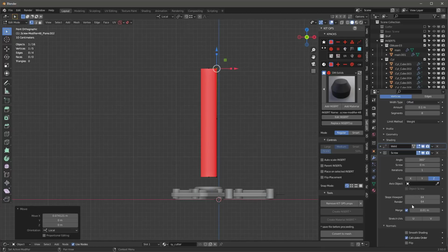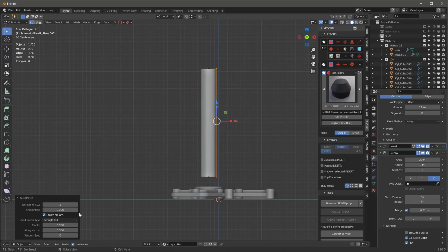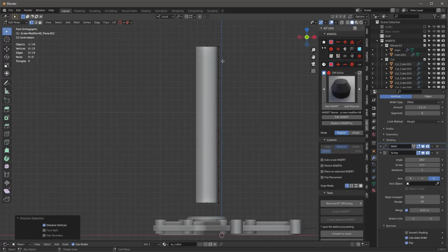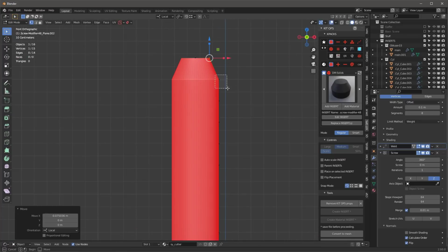Now notice I just flipped all my faces, so I need to hit this flip button right there to fix that. And then I can just select all of these and right click and say subdivide, and let's give us, I don't know, 6 of these, something like that. And if I want to delete any, I can just say Control X delete. And so let's just start massaging this.